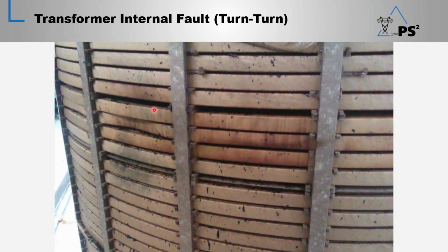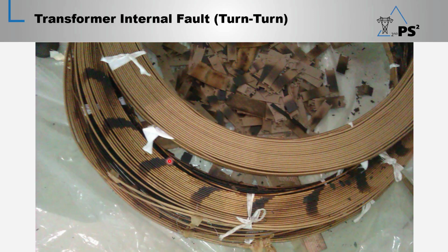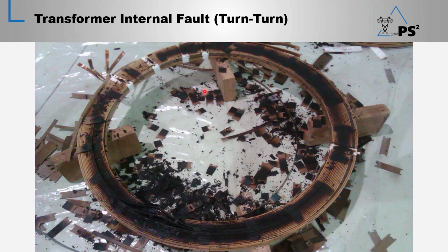So our study case number 1: here we have a transformer HV winding, it's disk continuous type, and there is a turn to turn fault, and we can see the inside of the winding already got burned, and there are forces on the winding. We can see this is the fault area. Here we can see the burn due to this short circuit current. Same we can see here, and this is the fault area.